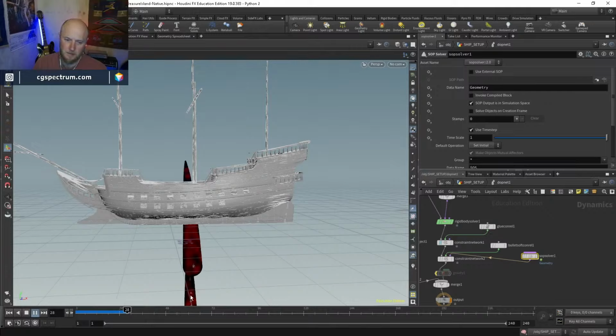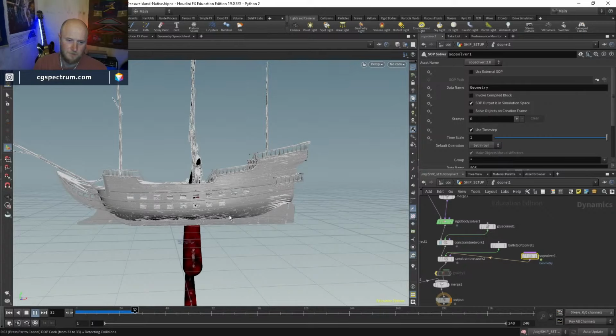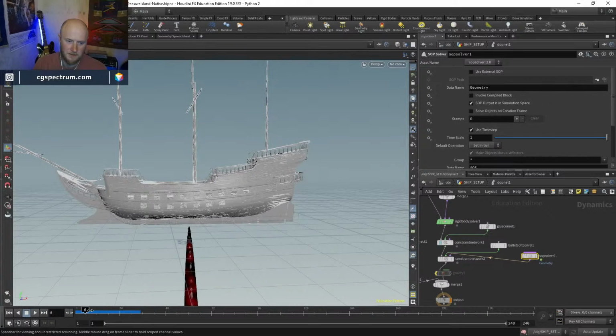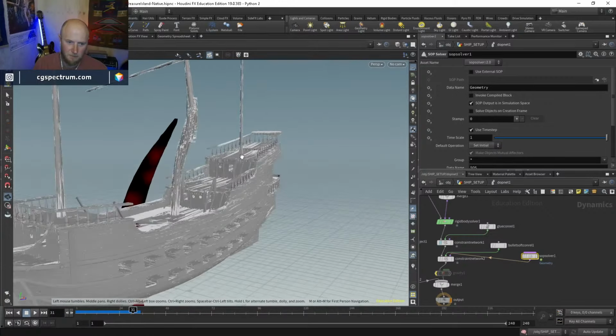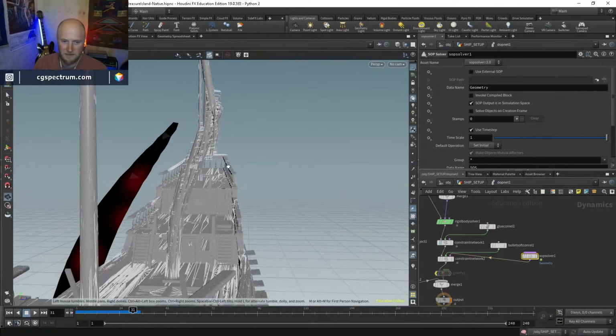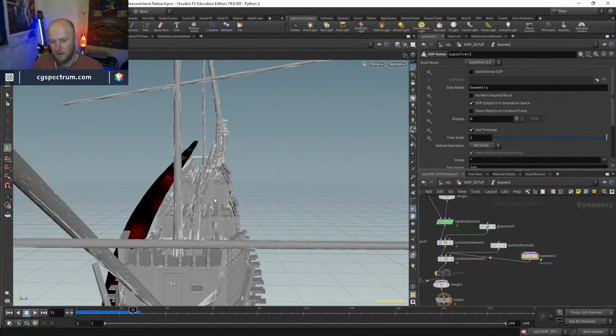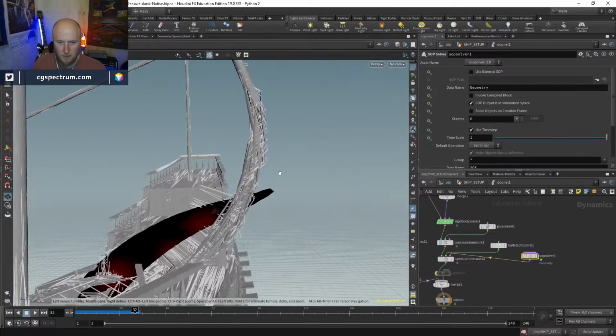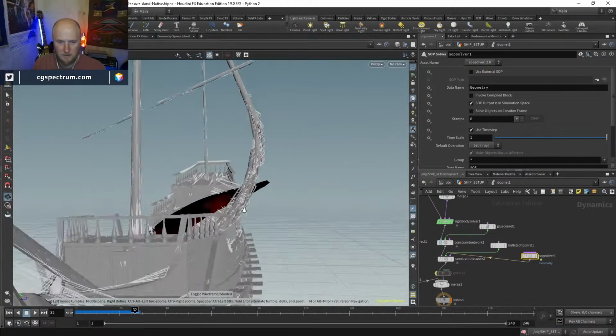Oh, this weird double tentacle here. It's probably going to shatter the mast. Nice. You can see how those constraints are hanging around a long time. So the angle stuff possibly is not the best, or maybe I've gone too high with that value, because you can see that we've got a very rubber looking mast here.